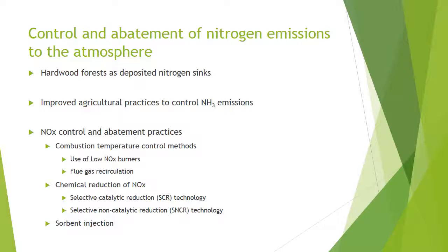Recirculation of flue gases reduces NOx in two ways. The flue gas in the combustion reaction dilutes the oxygen content of the gas stream being combusted, and the mass of the cooled flue gas stream also causes the heat of the gas stream being combusted to decrease below optimum NOx formation temperatures. There are two ways to chemically reduce NOx.